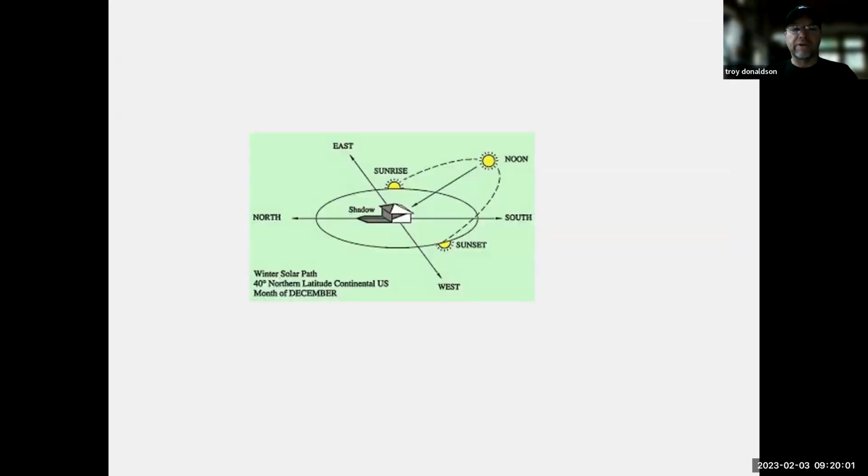The other thing I'm going to have you do is some solar angle work. This is the angle we're really looking for, and it can be called a number of different things. A lot of places call it the solar angle. Some call it the solar azimuth. This is a good graphic because this is the angle that we need, the angle from the sun to our location in comparison to the horizontal horizon. We want our solar panels to mount and be placed perpendicular to that angle.